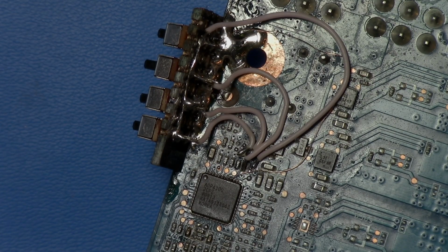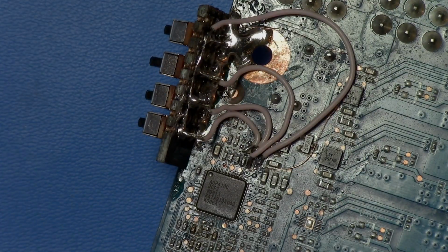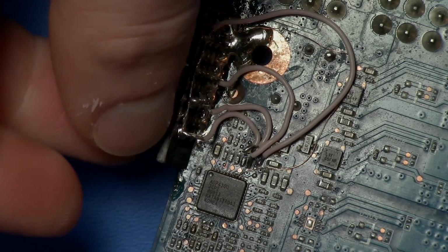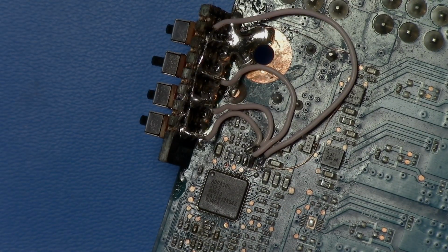So basically the extra bits here are just for a bit more resolution. And if you want to be able to get the really high voltages, getting well over 1.5 volts for sub-zero overclocking, you need the extra VIDs. Ideally, you want to get as high as possible, and then your trim pot just goes beyond that to maximize the voltage. But you really don't need more than 1.6 volts if you're not on LN2. 1.5 something is probably where most cards would max out anyways on something like dry ice or chilled liquids, like sub-zero liquid. So yeah, I think that pretty much covers it.